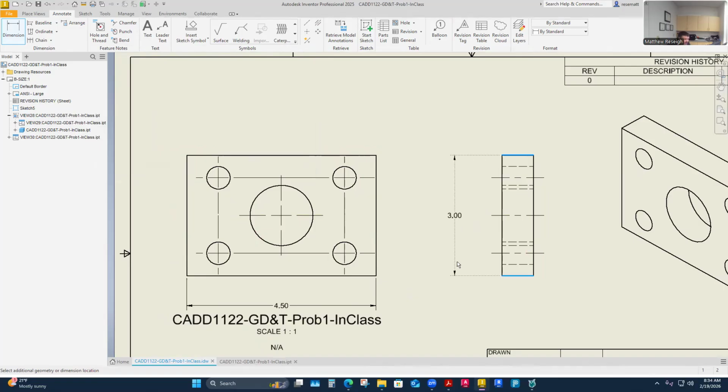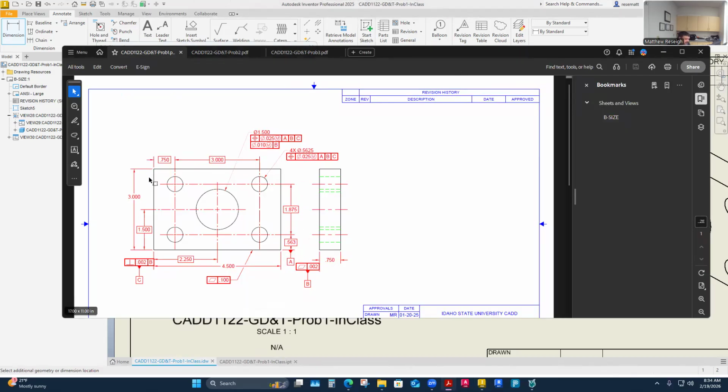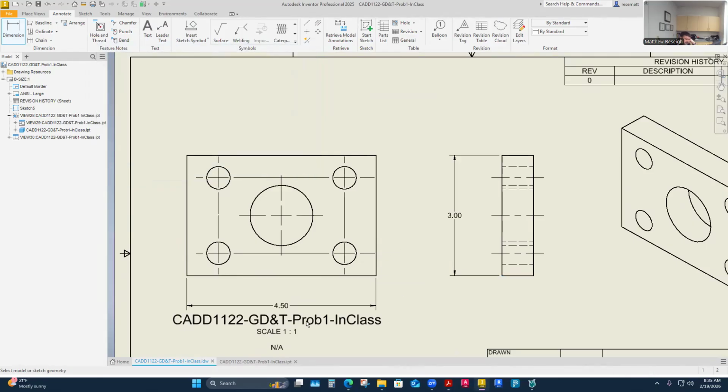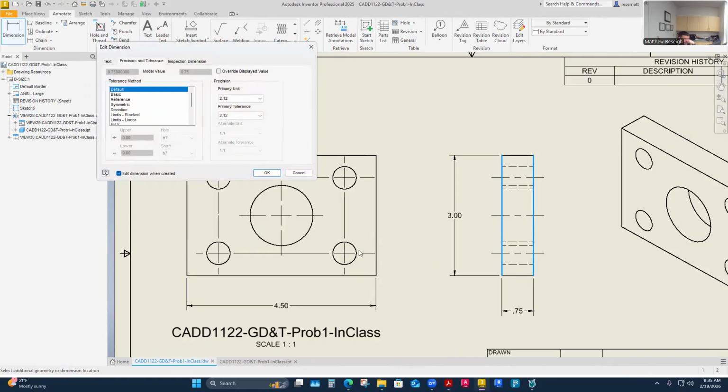I don't have a lot going on the right side view, and to me, it's also breaking even some of the drafting 101 rules in ASME, which is if you have multi-views, drop your dimensions in between views. So this 3 inches, I'm just moving to be in between views. This 1.5 inches, I'm going to try to move to be in between views. So I'm really going to pull these left side dimensions back in between, not going to worry about tolerancing them yet here or doing anything. Just get them snapped on there. So I've got that one, that one. Then I need an overall width, right? So maybe this is a great place to grab a width. Just pay attention whether you're grabbing endpoints or lines and make it intentional which one you're really trying to do.